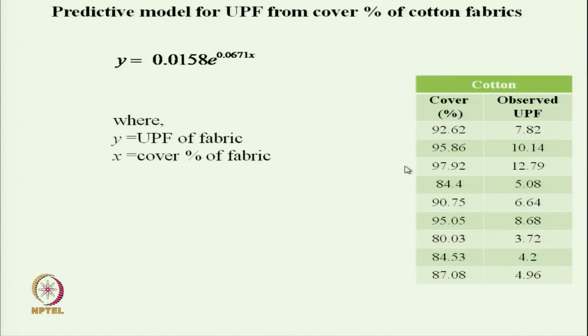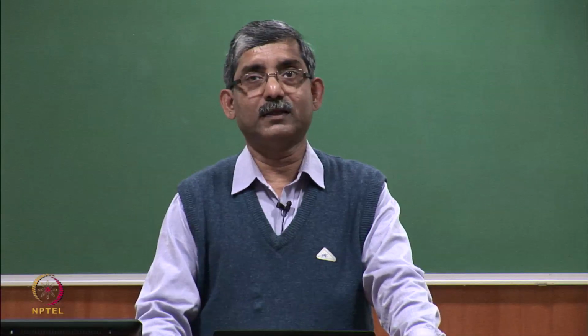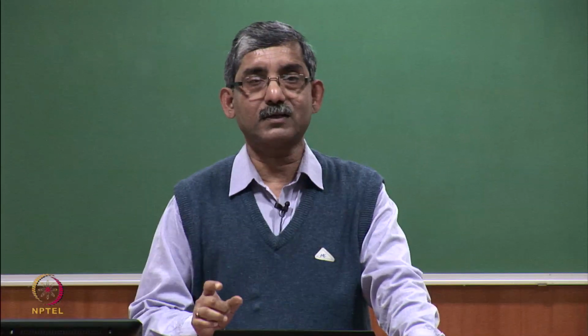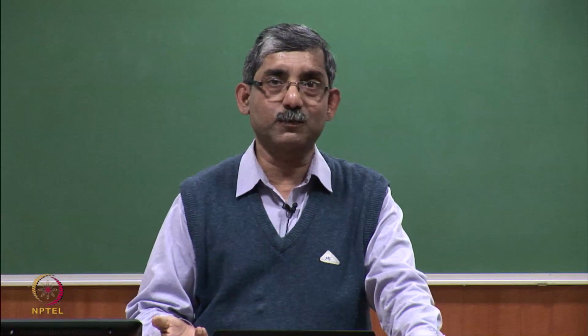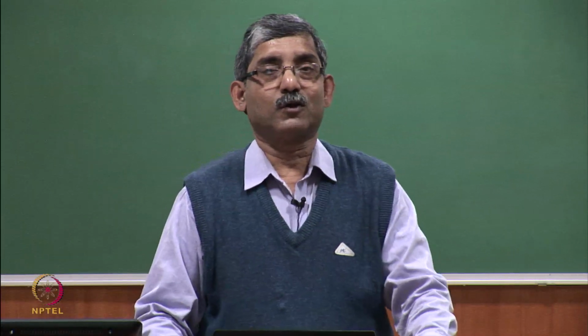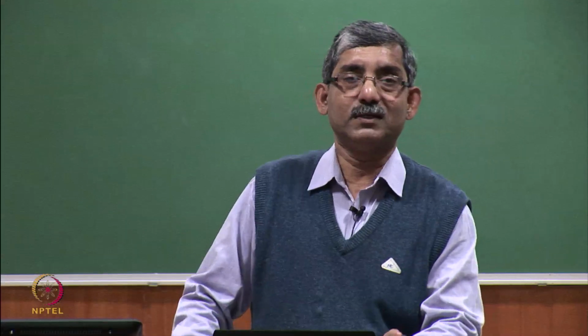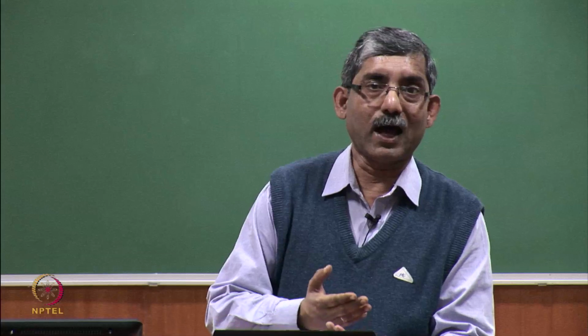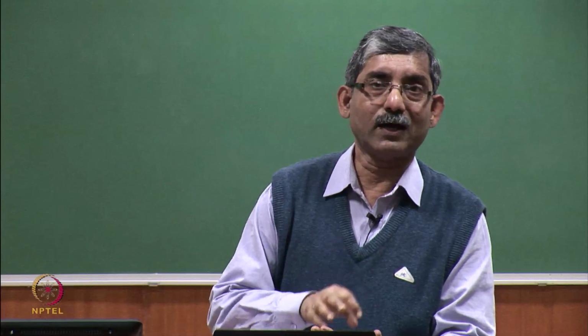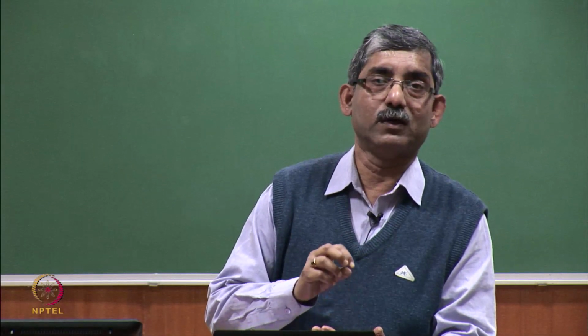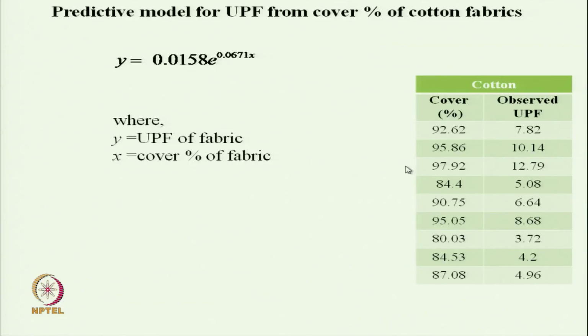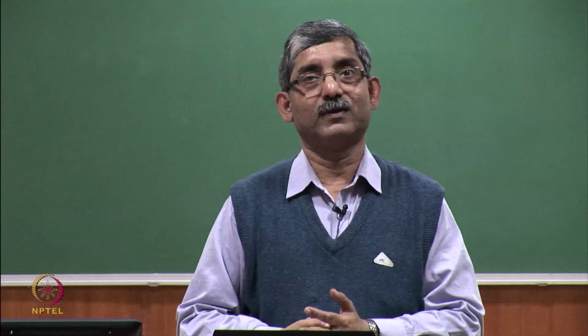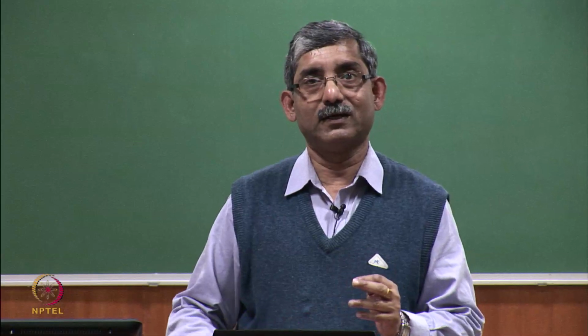Now, to predict the UPF value, we can use either cover as a parameter or mass per unit area as a parameter. Cover means the distance between threads; higher cover means higher protection, that means it will obstruct the UV rays from passing through.